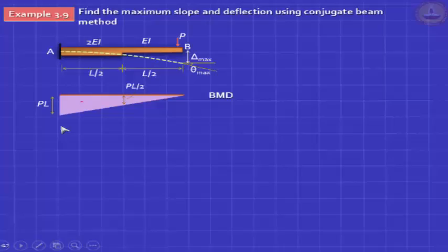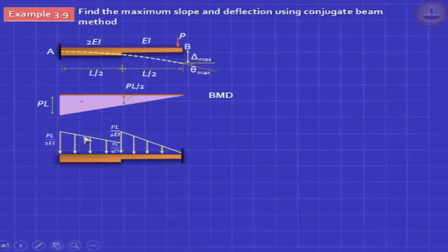So what do you have to do? First, draw the conjugate beam. The fixed end becomes free, the free end becomes fixed. All you need to do is to take this diagram, take every ordinate in it and divide it by the corresponding EI. So if you take this triangle on the right side, EI is constant, you will get a perfect triangle like this. But at this junction, the same bending moment will produce two different curvatures, one on the left, one on the right. Because on the right side, right means infinitesimally to the right, 1 nanomillimeter to the right.